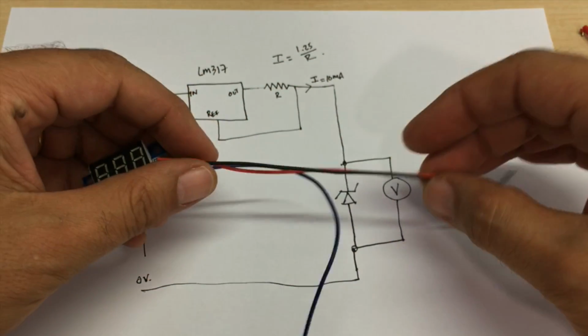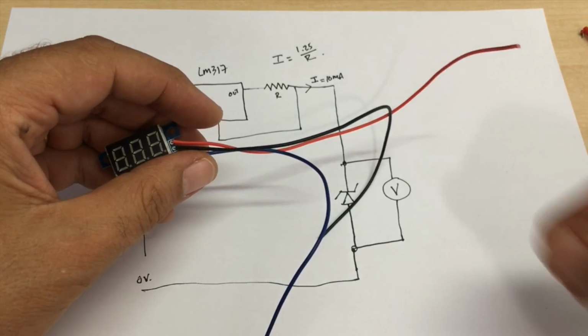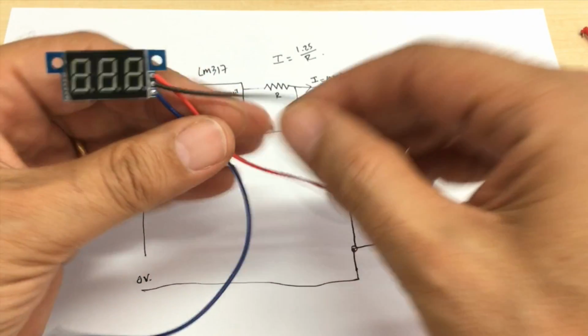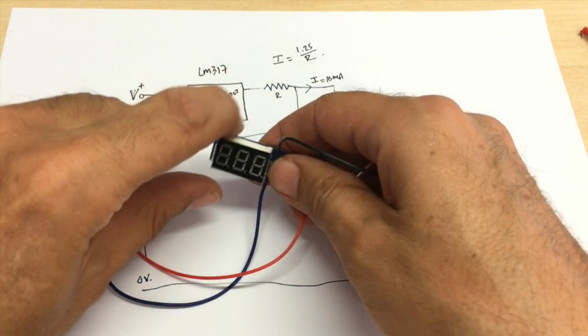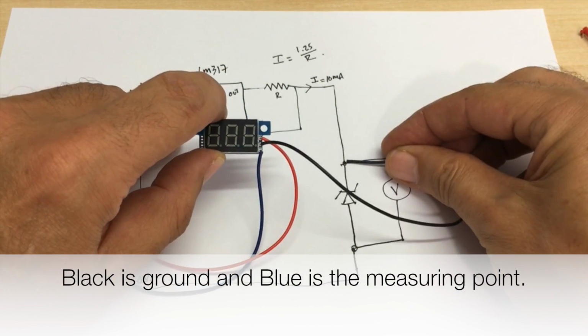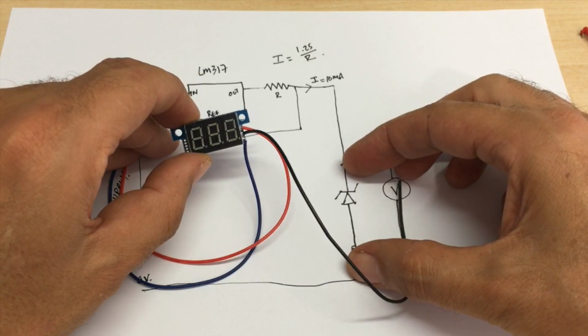And what it does is you connect your black one to ground, the red one to your positive supply. So that would be a supply. Let's call that the supply over here. You've got to be careful not to exceed it. I think the maximum is 30 volt supply. And this goes to the point you want to read. And what you're going to read is the voltage across there.